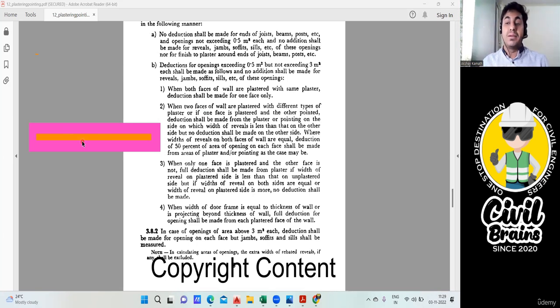When you come to the billing, in the sense you have to do the billing, no? You go to the site and you see how the window has been placed. If the window has been placed on the exterior side, I mean on this side, so here I'll not do any deduction for this wall. I'll not do the deduction. I'll do the deduction on this side of the wall. So we will go to the site and check it. But here in the estimation, we'll consider my window is exactly at the center.